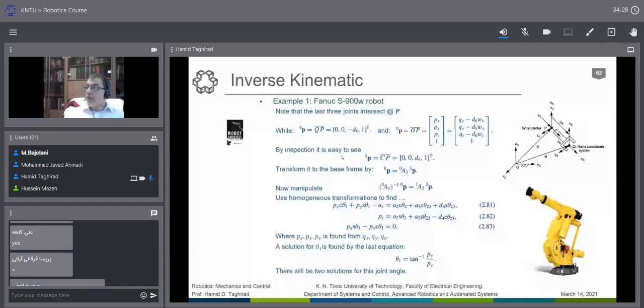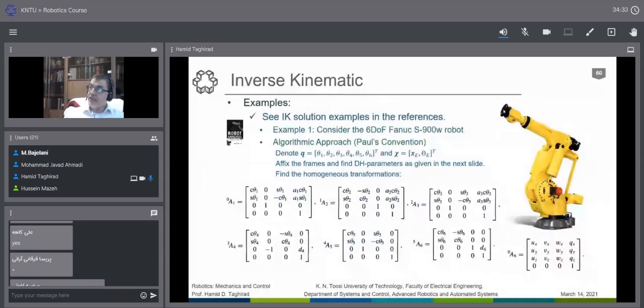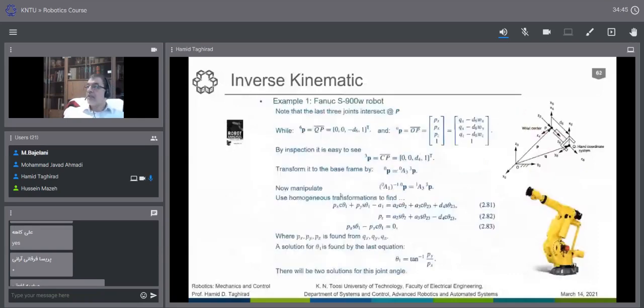So we see that we have an end effector and we have a wrist point. The wrist is where exactly these 3 axes are intersecting. We call it P or W, and we consider that P point to separate the orientation and the position. This P point, as you see here, Px, Py, Pz, can be very simply defined from the Q point.